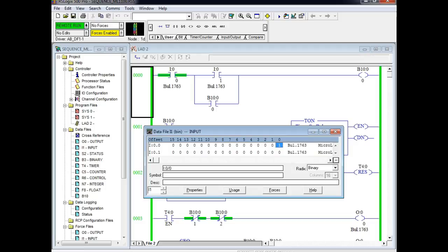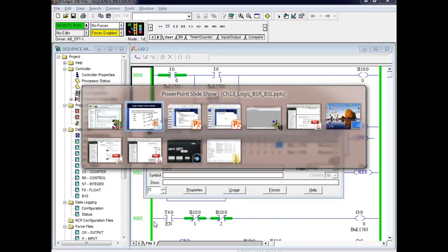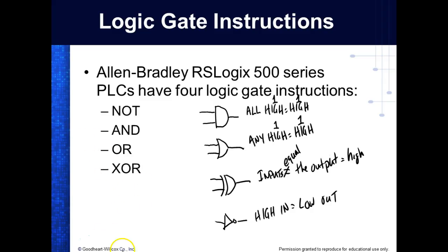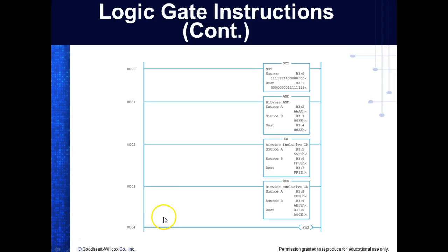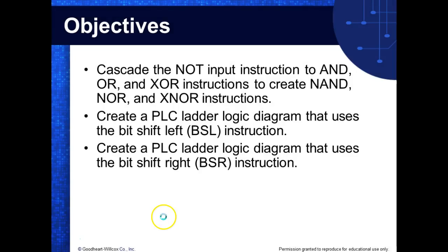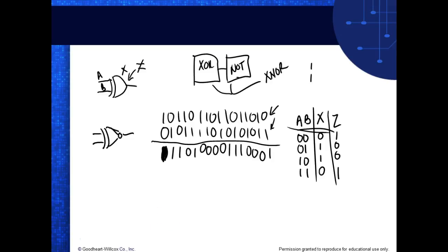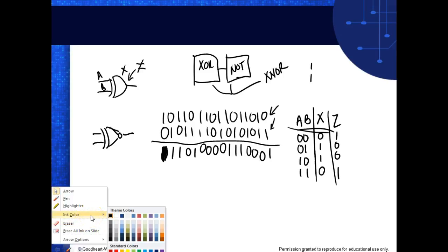What we're doing is we know we have to provide power, so we need 2 wires to provide power. Y'all understand that? So when we hook up, it depends on the PLC. When we hook up an input device, let's say I hook up a push button.